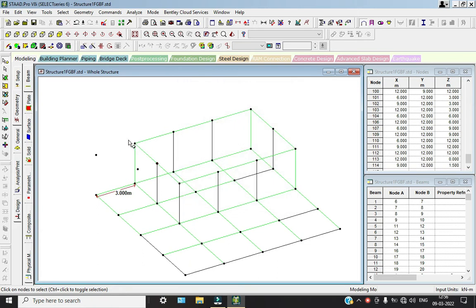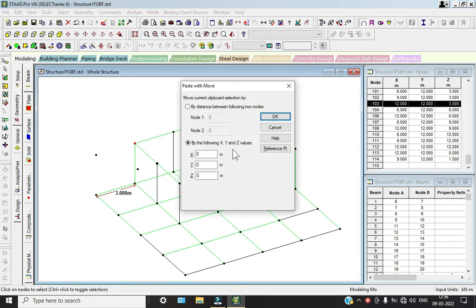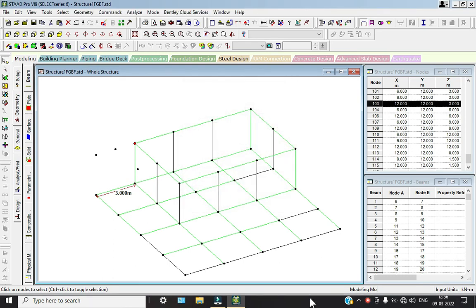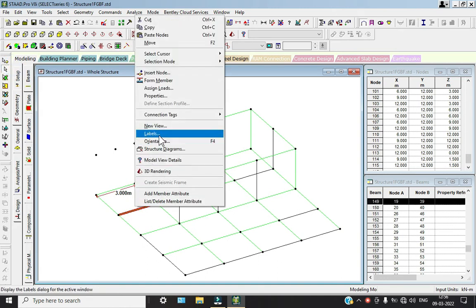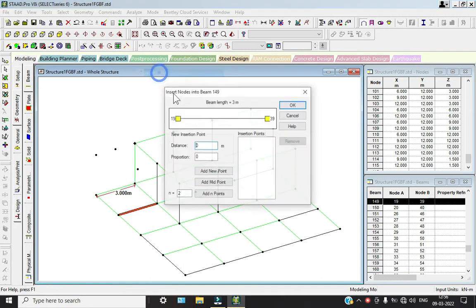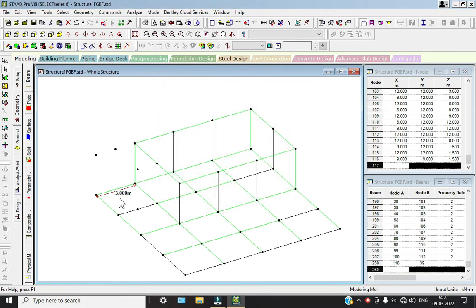So after that we are going to take the structure. So if we select geometry, we see properties. So we have to go to thickness. So we want to add 0.3, enter and close. So select assign to view, assign and yes. So we see over here, so we got our steps for our swimming pool.